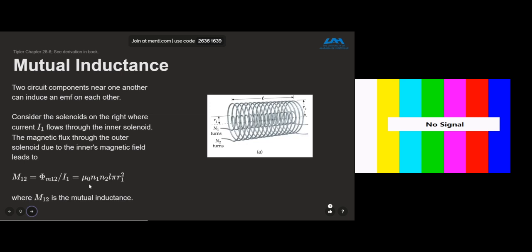It's more or less the same thing here. Inductance is not changed by how much current you have flowing through it. You always end up dividing by the current, and so it is current independent. If you know what the inductance is for 1 amp and you ramp up your current to 2 amps, you still have the exact same inductance.